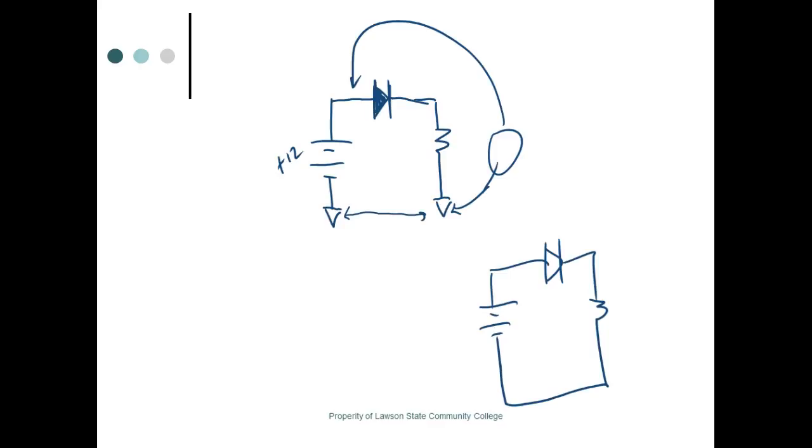What people don't understand is that the more wires we put in a schematic, the more cumbersome it gets, where everything is hooked to a common. They might have a different source, but everything would be hooked to a common. So instead of drawing the wire that represents the common and drawing everything connected to it, we use a symbol to represent a wire. But the wire has to be there.